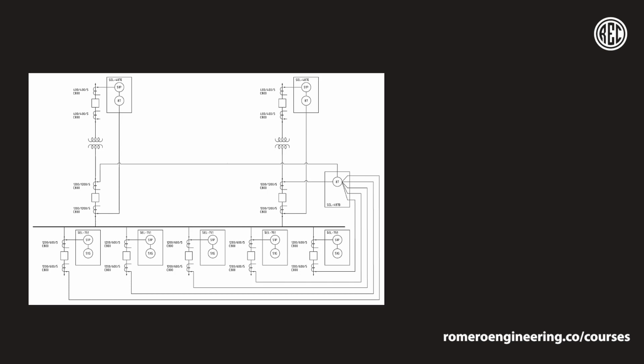In a current differential scheme, the current on all circuits connected to the bus needs to be measured, and then we're going to be comparing the currents that are entering and leaving the bus to determine if there's a fault in the bus. Now, in practical applications, this presents a problem because all the current transformers, or CTs, need to accurately replicate the currents that are entering and leaving the bus.